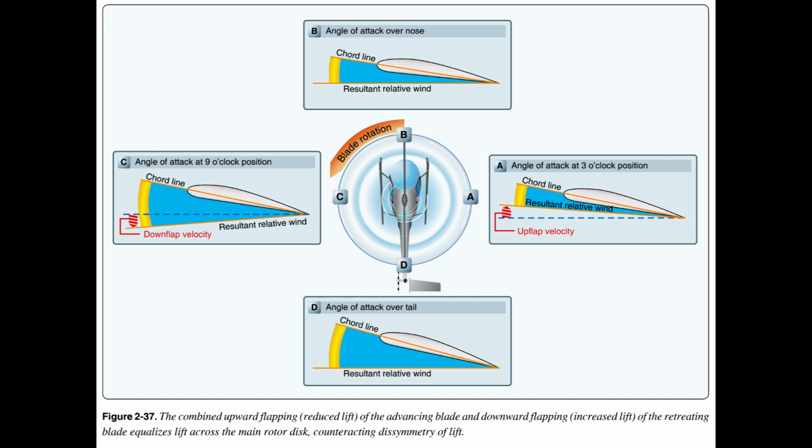If the nose is permitted to pitch up while passing through this speed range, the aircraft may also tend to roll to the right. To correct for this tendency, the pilot must continuously move the cyclic forward as velocity of the helicopter increases until the takeoff is complete, and the helicopter has transitioned into forward flight. End of page 2-20.